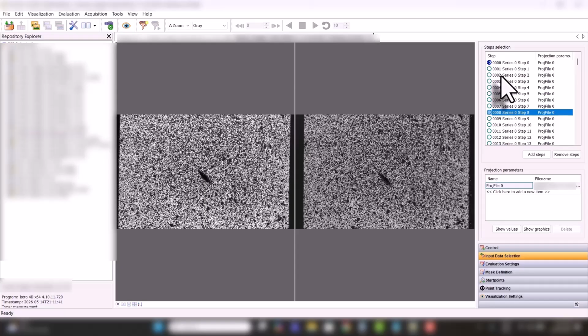That's going to be the initial image, step 0 anyway. So the general idea is that step 0 for a DIC image series is the reference step, and there's only one reference step. There's always a single reference step. So conceptually, there's this one primary reference image for the correlation, the reference step, and all subsequent images are fundamentally related back to that reference image.